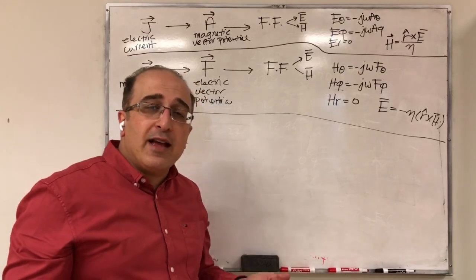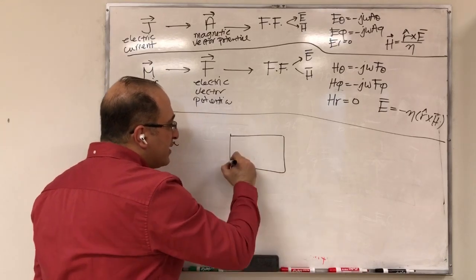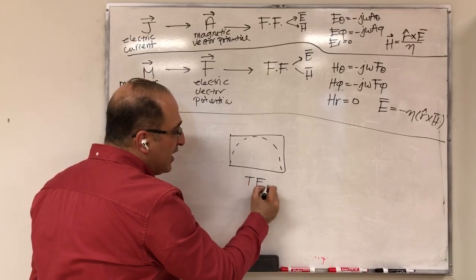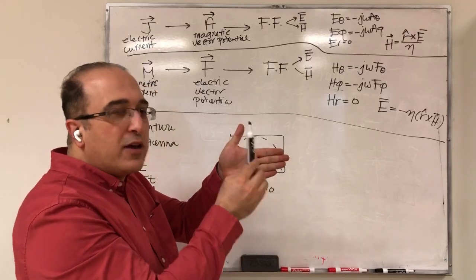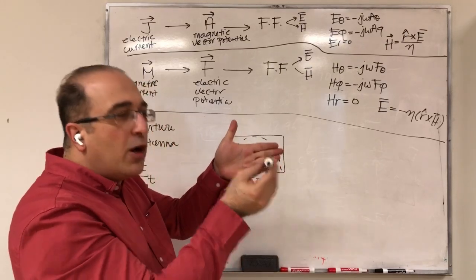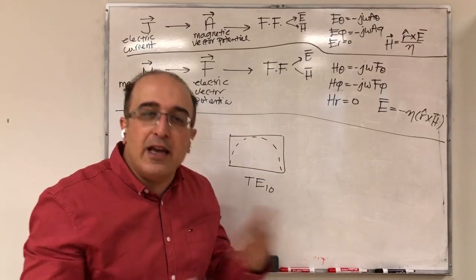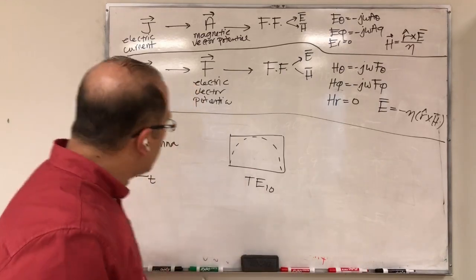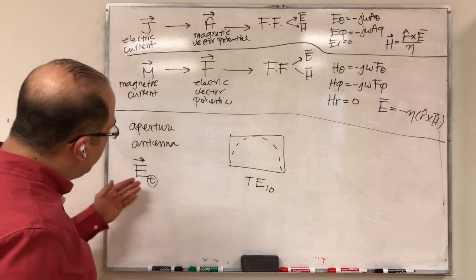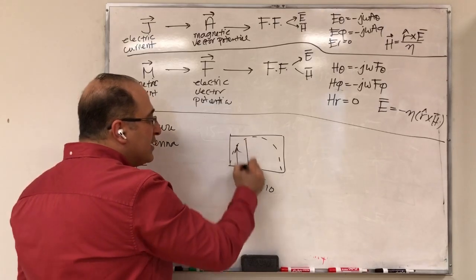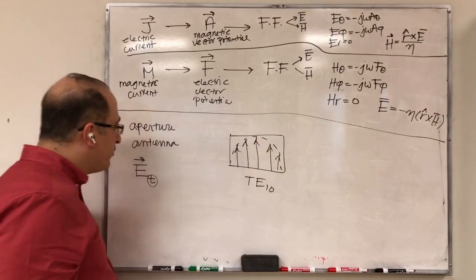For our waveguide antenna, that doesn't really matter, because remember, the waveguide that we consider is this waveguide, and this is TE10, and TE means electric field is transverse to the direction of propagation. That means electric field does not have any component here. So the electric field that remains is already tangential to the aperture anyway for this mode that we are considering. So this small t that sometimes you see in my notes is related to the fact that I'm assuming the only thing you need is electric field tangential to the aperture. You don't need, for example, to know this electric field over the aperture.